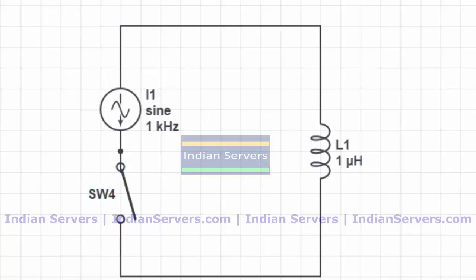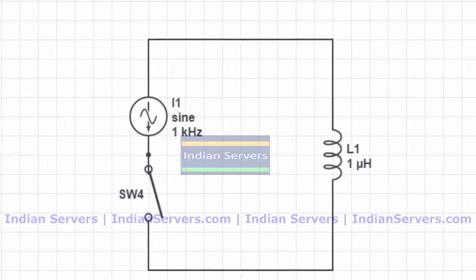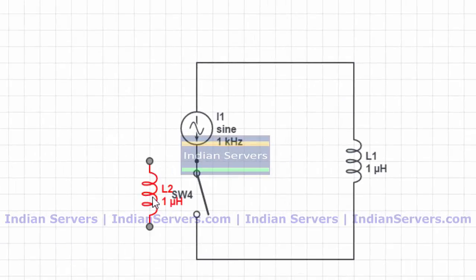So simply I will place a magnet here, an electromagnet. If we replace this switch with a transistor, the transistor may get damaged because a transistor can bear up to some 20 or 25 volts. But here I am using 230 volts AC.